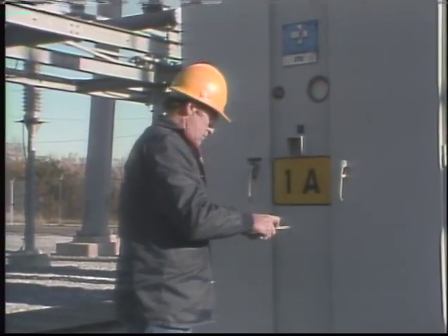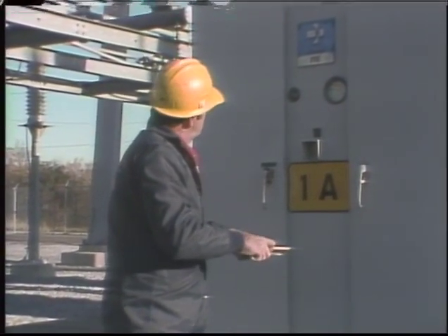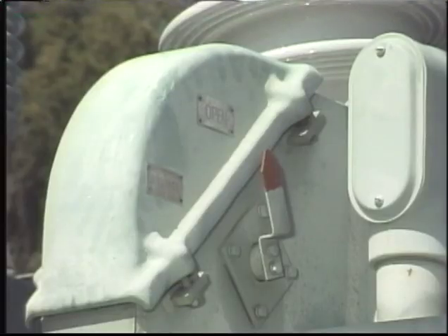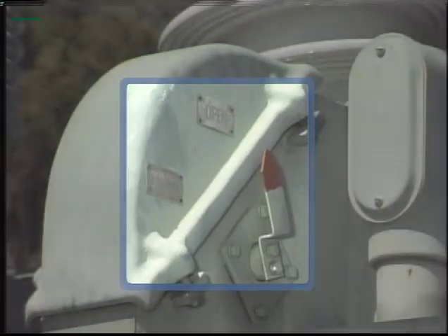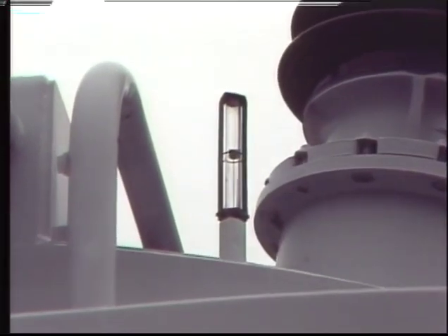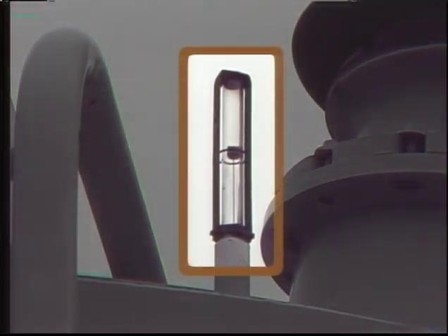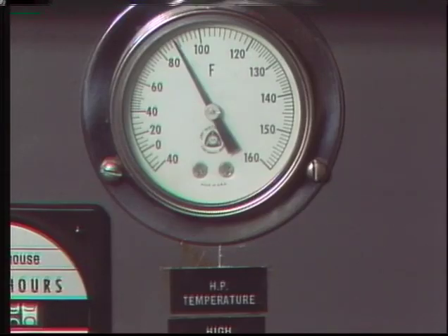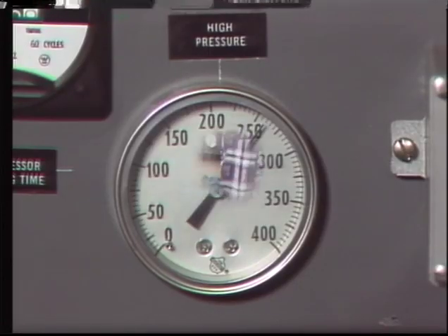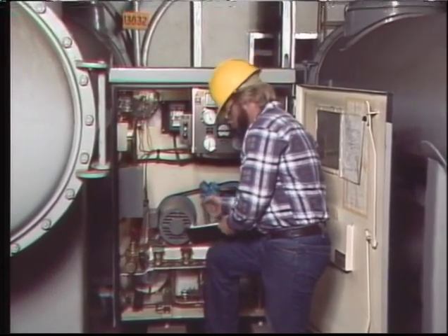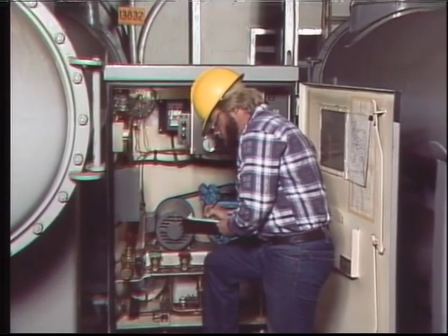In addition, breakers typically have various indicators that should be checked and documented. One of these is the position indicator that indicates whether the breaker is open or closed. An operation counter keeps track of the number of times a breaker has operated. The counter number is recorded. Other indications that should be checked and noted can include gauge readings, such as an oil level indication, temperature indications, and pressure indications. It's important to document your observations thoroughly and accurately.